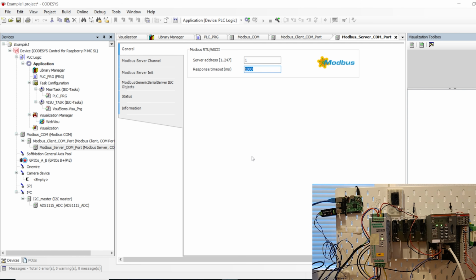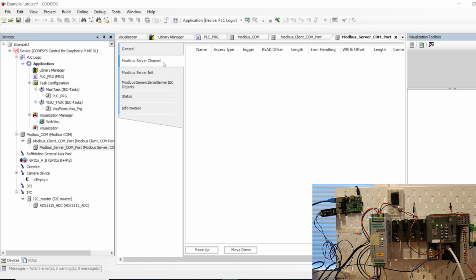Here also there are 2 approaches. We've seen some of the approaches before. You can either use Modbus channels, or you can use function blocks. Function blocks are more flexible. You write them in any language you want, and then you can change parameters during runtime. There is a library dedicated to configuring this communication. But if you're really in a hurry, channels also come in handy. So we're going to use channels in this tutorial.